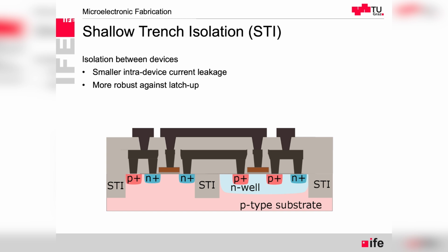So we were talking about this planarization, where everything we would like to be very flat. And this old technology was not good enough, and also was not going far enough into the substrates to enable really good isolation. So the new development from LOCOS is this STI, and what we see is that everywhere where we don't have gate and we don't have P or N diffusion, all the rest of spaces are filled with this STI. That could be silicon dioxide, but more often it will be silicon nitride with a layer of silicon dioxide.